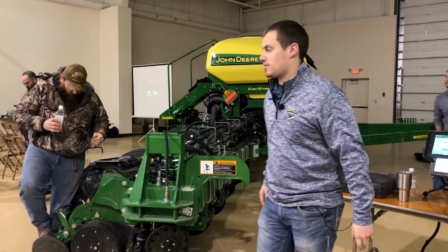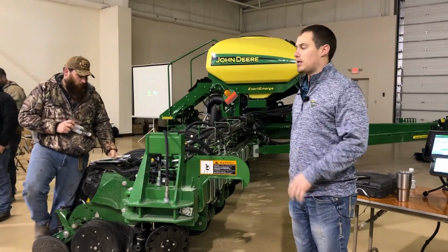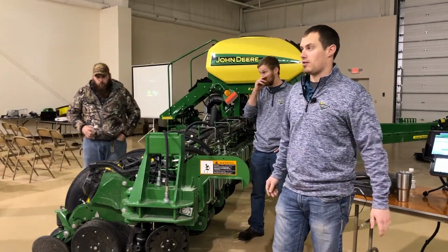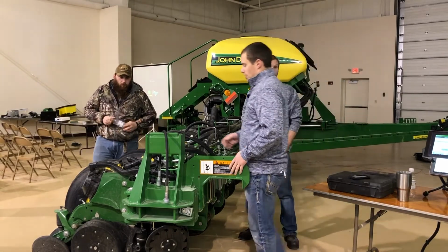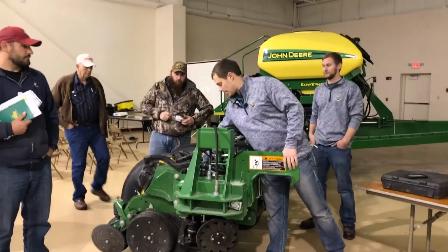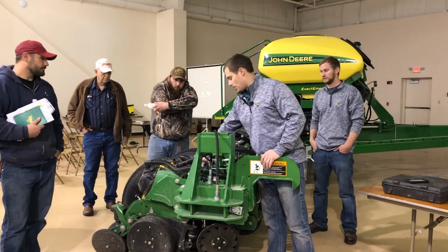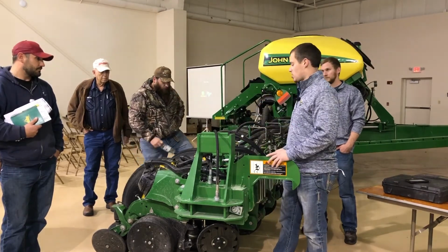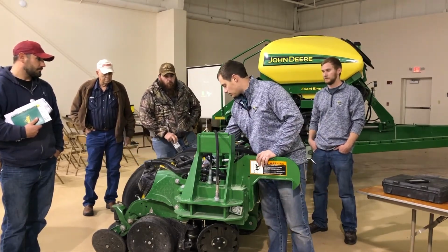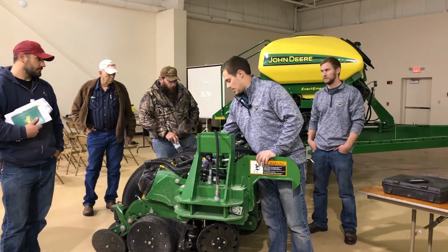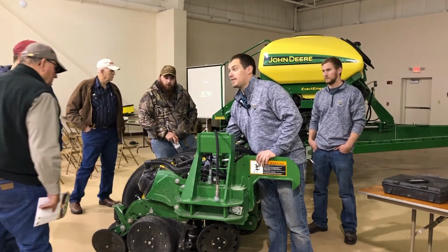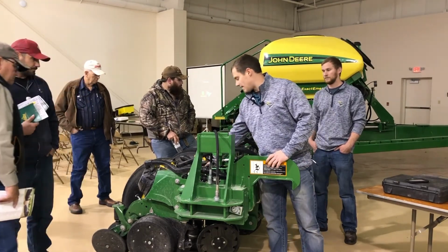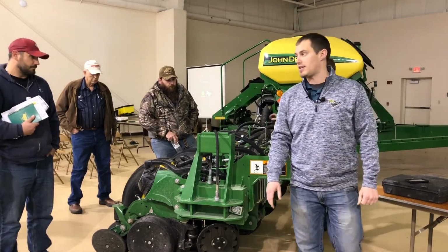Alright, well, I'm first going to start out here with our row unit and talk about just a few components that we have with this hydraulic system. Right here we have our hydraulic actuator, and like I said, John listed them all off, so I'm just going to point to them. With this hydraulic actuator, we have an accumulator here that helps absorb that shock. And then we have our pressure sensor right here, as well as the downforce valve coil here. That valve coil is what's doing all the changes at that 5 times a second.